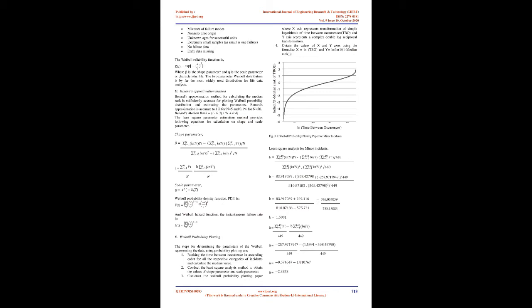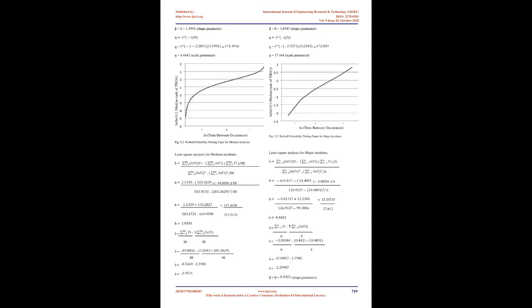Refinery processes in operation. The basic job of a refinery is to separate crude oil into hydrocarbon groups, or fractions, and transform each fraction into a useful product. Thus, much of the refining process, after the initial separation of crude oil into hydrocarbon fractions, consists of manipulating the molecular structure of oil to convert heavier fractions into lighter ones. Crude oil is delivered from production wells, sites where oil is pumped from the ground, to refineries by pipeline, tanker, ship, rail, or truck. There are 4 basic steps in the refining process: separation, conversion, treating and blending.